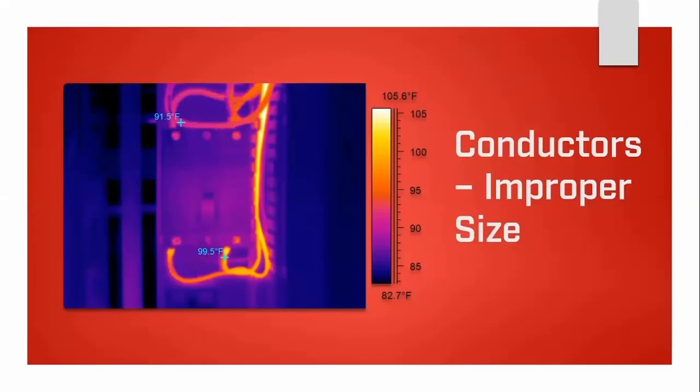When we've got a poor installation, conductors or cables of the wrong size, this is a 40 amp molded case circuit breaker used on a machine for a disconnect. The breaker is 3-phase, but only 2 of the phases are actually used. If we notice the heat on the load wires in comparison to the line conductors, it's certainly a sign to look a bit deeper. Even in the infrared image, the load conductors appear smaller than the line. The line is diameter 6 and the load is diameter 12.